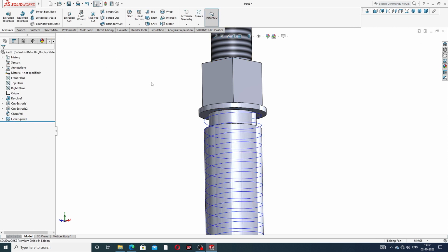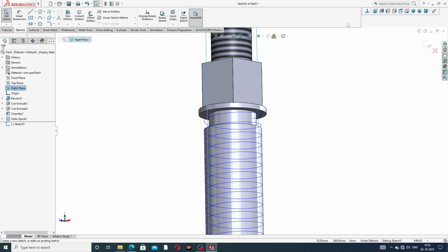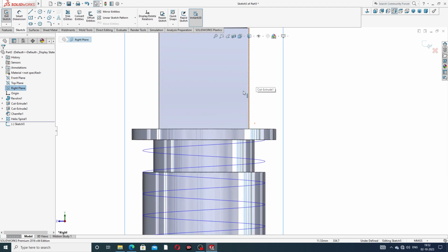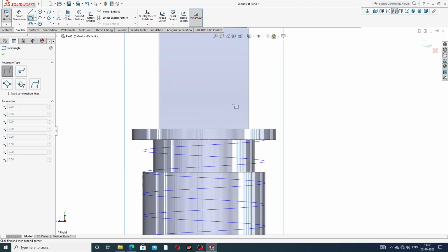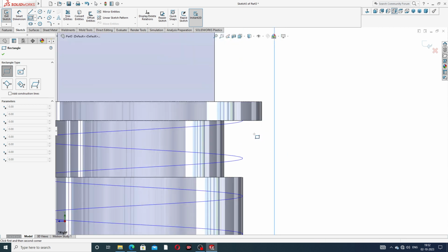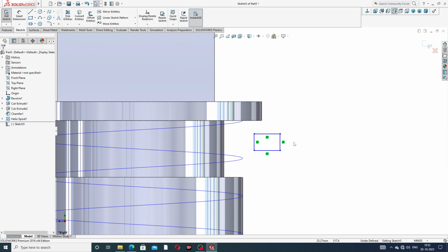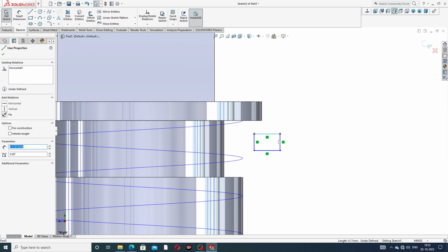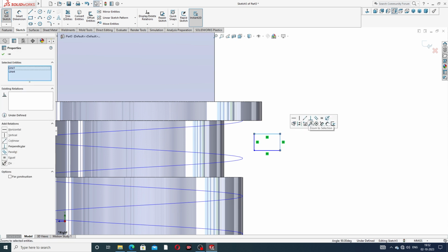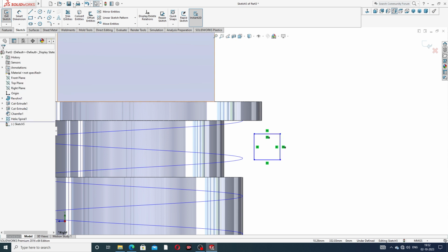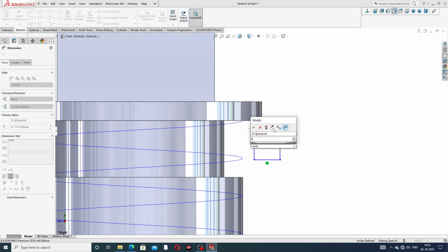And okay, and use a right plane sketch, normal. Okay, and draw a corner rectangle, and drawing a corner rectangle is this, and this is a both line select here and equal, and dimension is used here, a 3 millimeter is perfect.